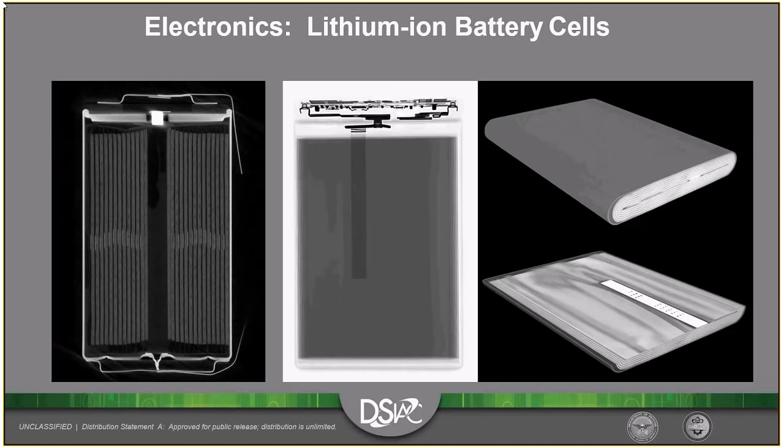You can model the battery into a surface model and take it to another software and perform stress analysis on that as a scanned data set. So if you have a battery that was punctured, you can go in, pull those surfaces out, export that to an external software and perform some stress analysis in that sense. But directly from the CT data, you just have a volumetric data set, so you'd have to pull what you need from that to then move on and do your stress analysis in another software.